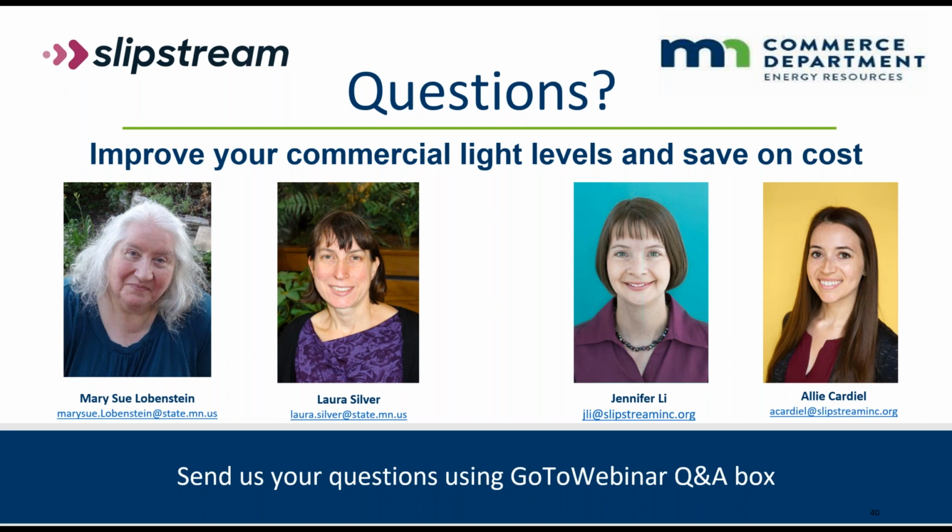But in a nutshell, what we did was obviously try to minimize the amount of natural light in the space by, say, closing blinds. We also then took light levels with the lights on and then immediately with the lights off. By taking the difference of those two light meter measurements, it helped us to isolate how much lighting in a space was being contributed by natural light and how much by the electric lights.